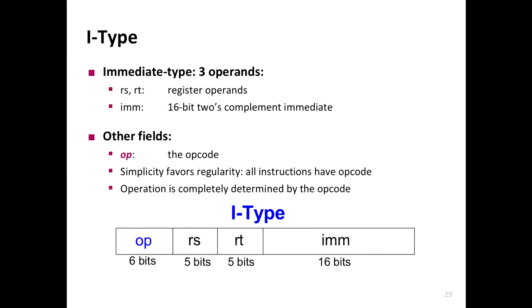We are now going to see what changes one has to make to the register file and the ALU to incorporate the I-type instruction, because you have registers and you need an immediate value. Remember that the address for a load word, for example, is computed using the ALU on the immediate value and the register operand value. So we need to make some modifications to the ALU and the register file.